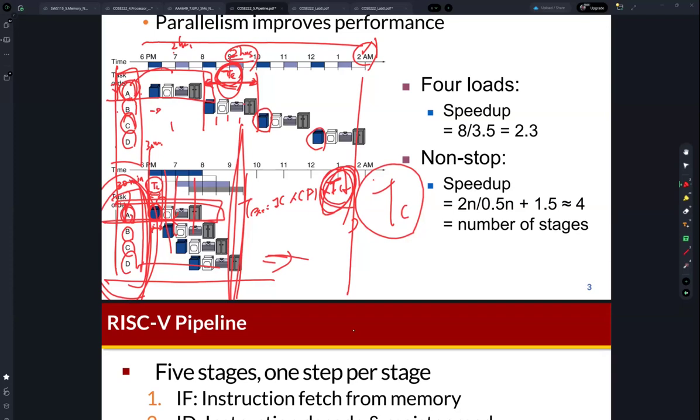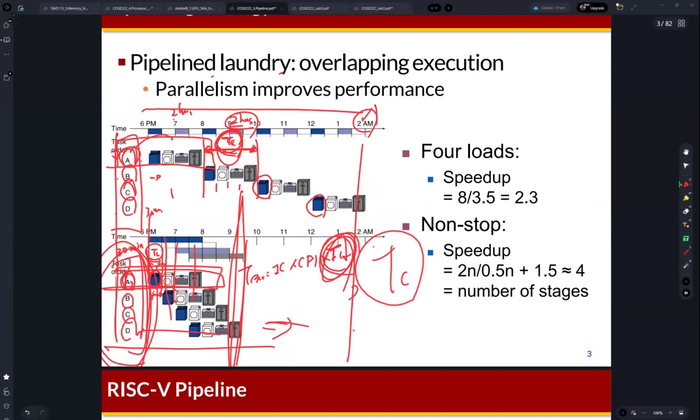There are many tasks, and in the single cycle processor design, in order to execute a single instruction, there are multiple steps, the 5 steps, right? So instruction fetch, instruction decoding, execution, memory, and write back. So we can apply pipelines to this processor design. For what? To improve the performance, right? Because we can reduce the TC.